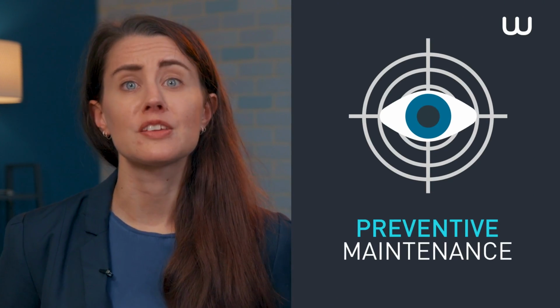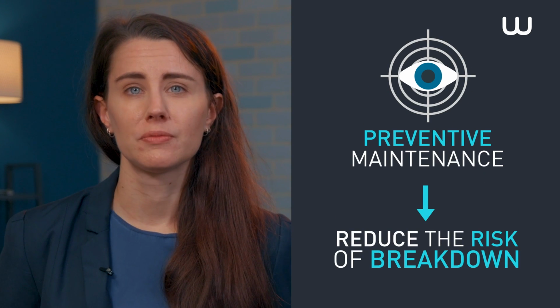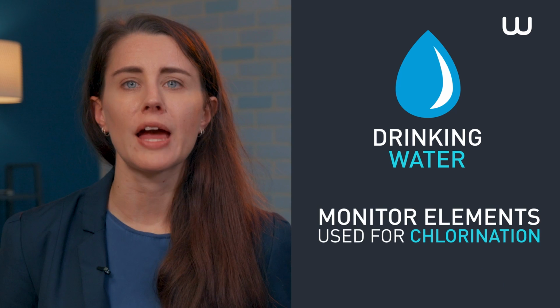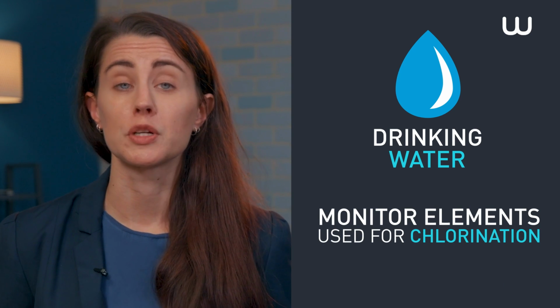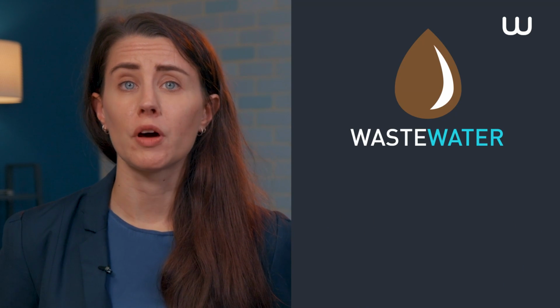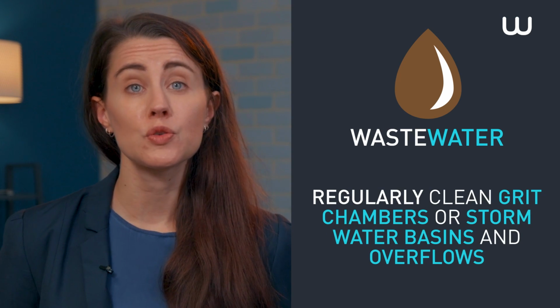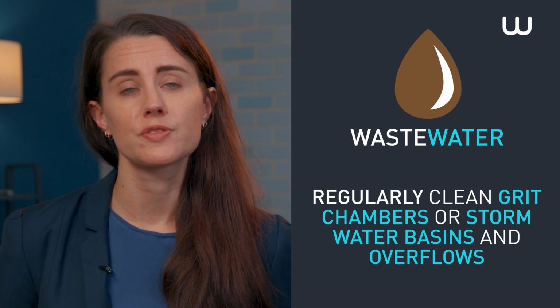The main points to be remembered. The objective of preventive maintenance is to reduce the risk of breakdown. For drinking water, it is important to regularly monitor elements used for chlorination, for example. For wastewater, it is necessary to regularly clean grit chambers or stormwater basins and overflows, for example.